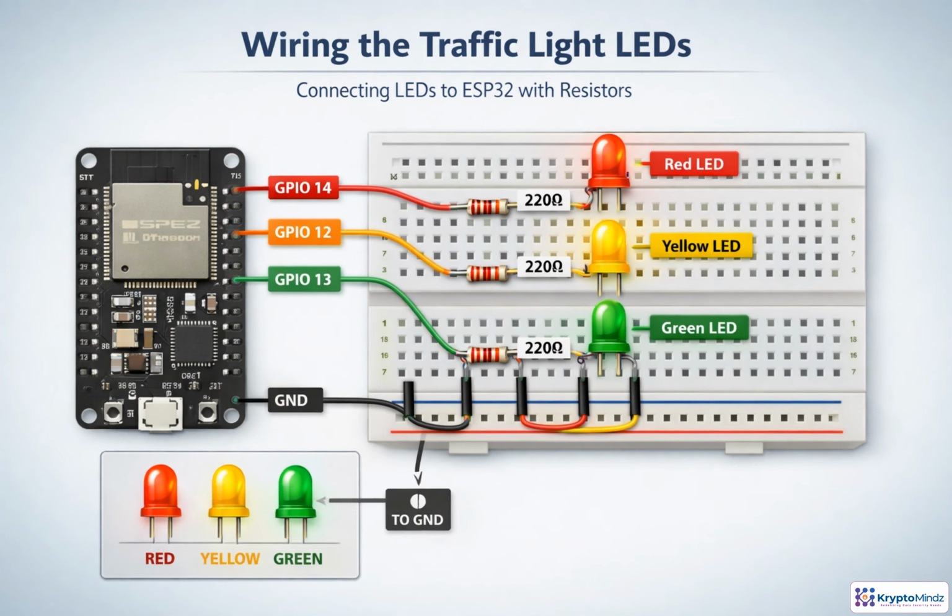For each traffic light LED, the ESP32 output drives the anode through a current-limiting resistor. Start with the red LED, then repeat the same pattern for yellow and green, using a separate GPIO pin for each one. The cathode side of every LED goes back to ground, creating a common return path. Match wire colors to the LED colors, and use black for ground. Before powering up, check resistor placement and LED polarity. A reversed LED simply will not light.